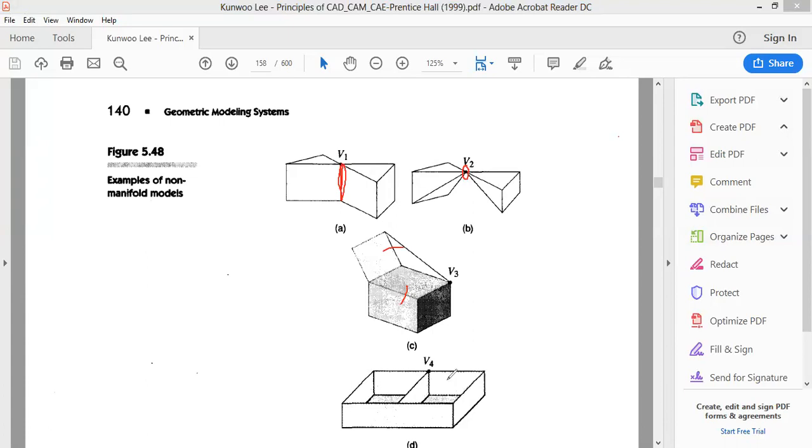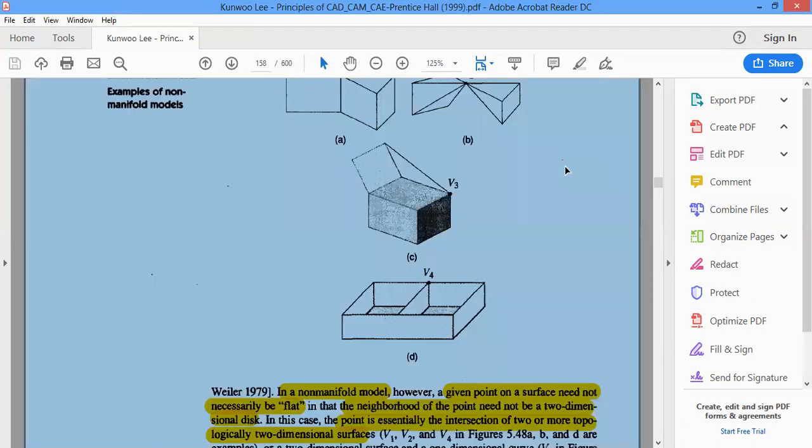We would have seen this especially when architects use this, where there will not be any thickness for this. If we have to do the same thing in a solid modeling module, then we have to make use of thin sections, and give the thickness of this. Here we don't need to give that. So in that situation, it is going to become a non-manifold structure. This is going to come into the picture every time.